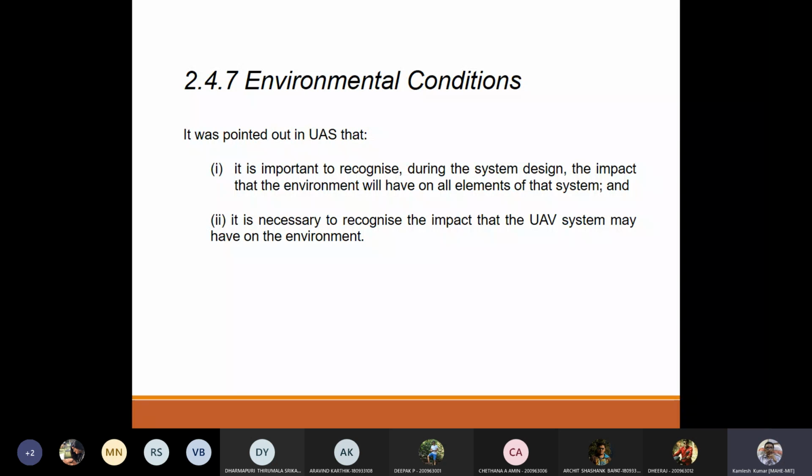Netra failed, I remember. I was there during the meeting. Netra failed because of the gyro sensors. The gyro sensor was affected, the compass was affected because of the soil itself. And they were not getting what the reason was. They were thinking that the sensor is having a problem or maybe the system is not supporting. Later they realized the area is also a problem. That complete area had a different soil, and that soil has a magnetism property which was affecting the compass.